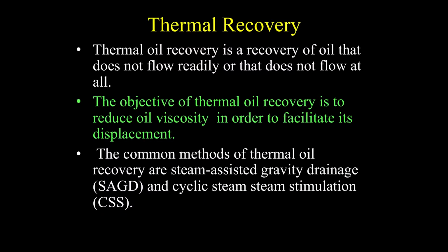Thermal oil recovery is a recovery of oil that does not flow readily or that does not flow at all. The objective of thermal oil recovery is to reduce oil viscosity in order to facilitate its displacement. The common methods of thermal oil recovery are steam-assisted gravity drainage and cyclic steam stimulation.